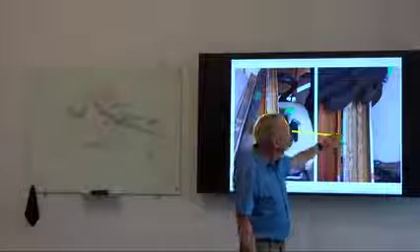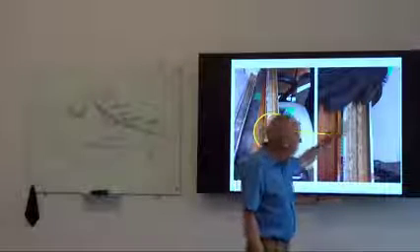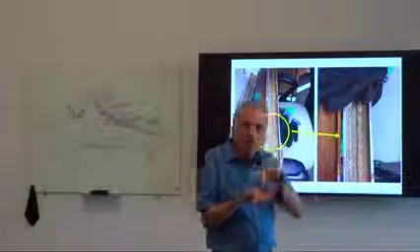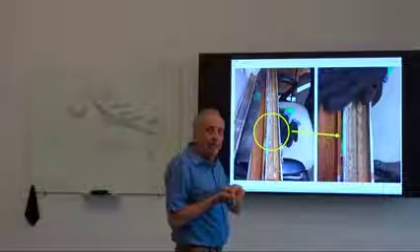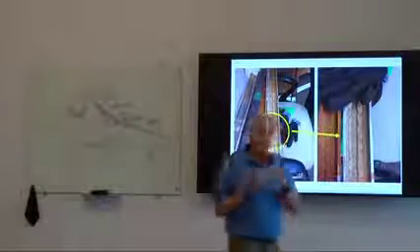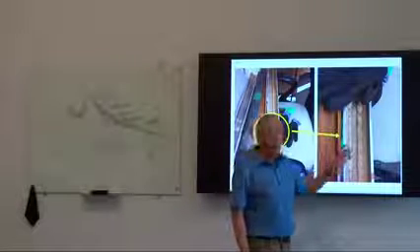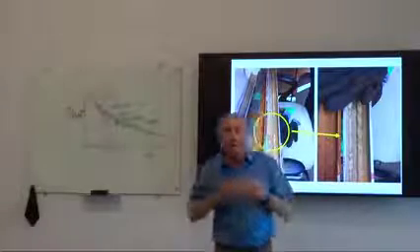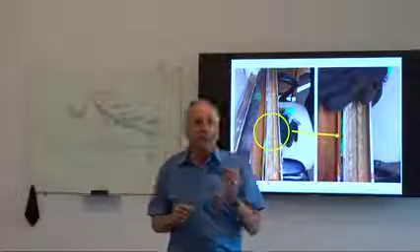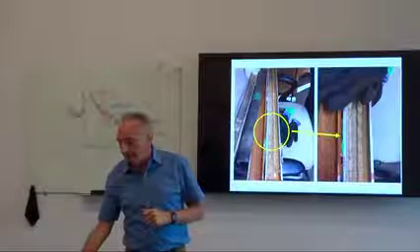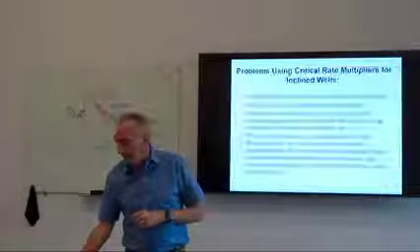And here we've just zoomed in and looked at it a little bit more closely. What we had was water running down this lower center section of the tubing, and where the gas was interfacing against the liquid, we got formation of scale on the banks of that river. If we think about it as a little river down the center, then we were forming scale in that contact zone between the gas and the liquid.